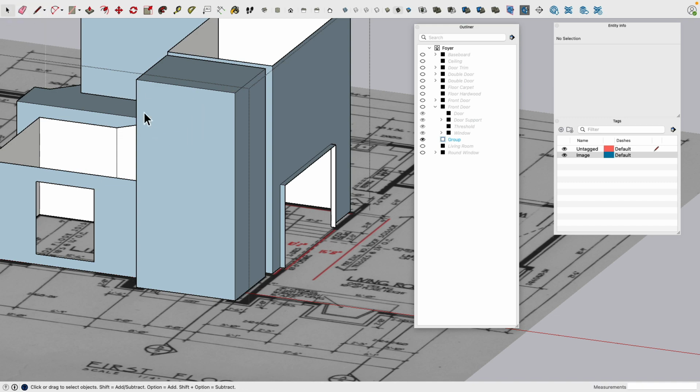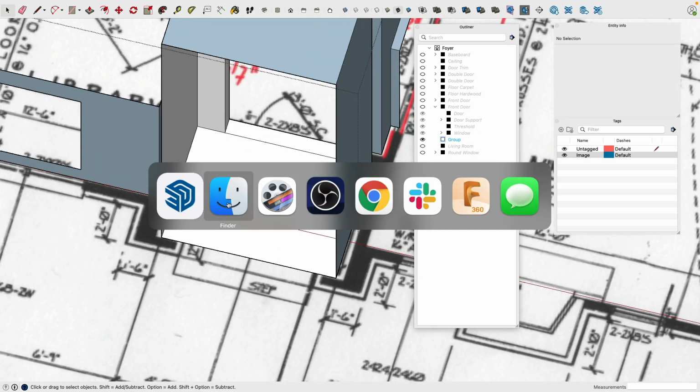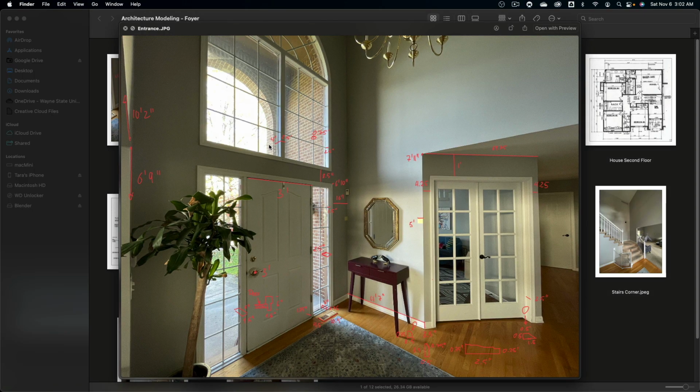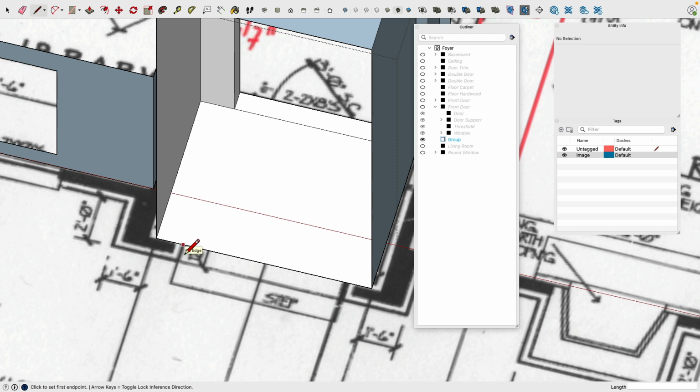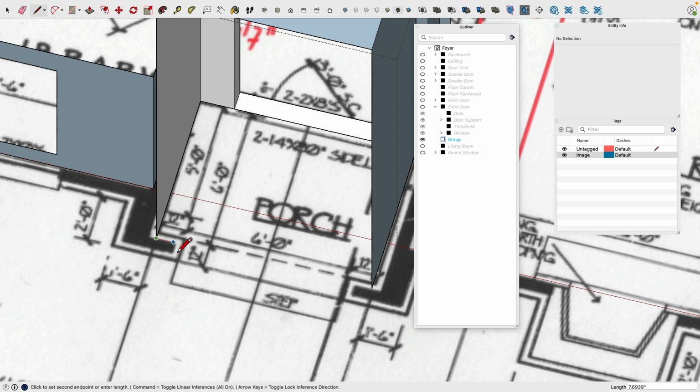Then this front face we want to remove. Do we see this extrusion? Yeah, let's put at least this piece in. How much is this actually? Let's say this way, 12. 12 feet. Okay, sorry, 12 inches. I will delete this edge. So this one I bring over by 12. Then I will do the same on the other side.